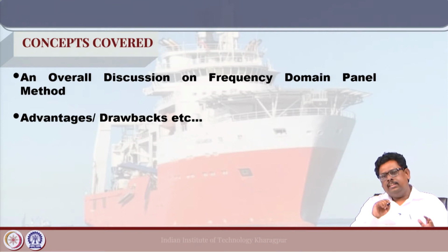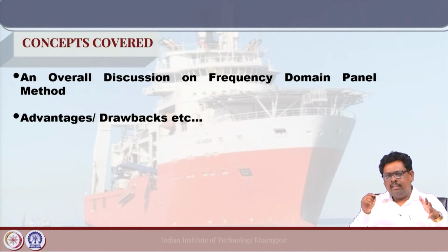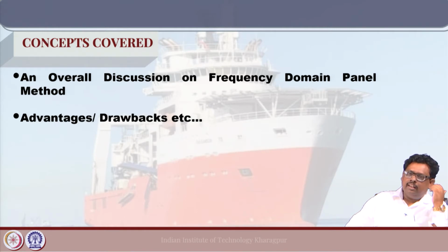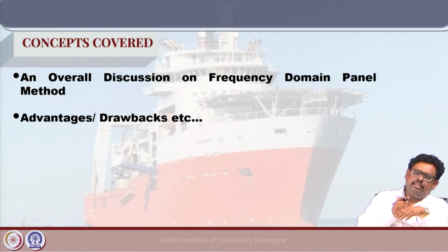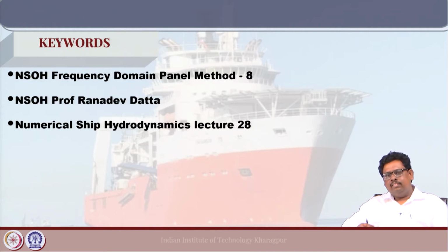Now, by this time we all know the basic principle of the frequency domain panel method, how it discretizes the whole domain, how we can perform the integration of the Rankine part, which is 1 upon R, and also how we integrate the other part. Some slides we are still going to see today, because those are key things of this frequency domain panel method. These are the keywords that we are going to use in this lecture. So, let us start.